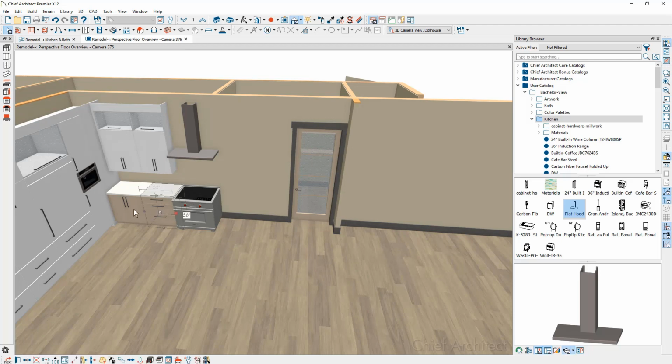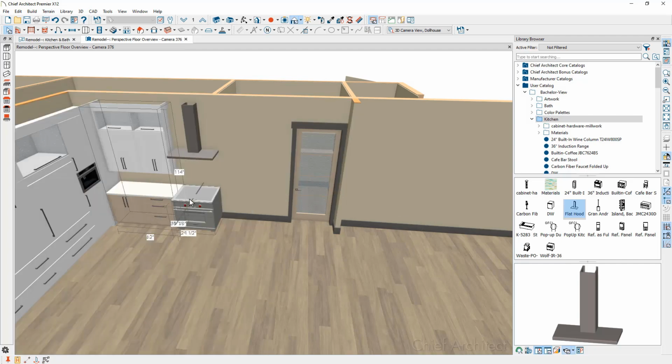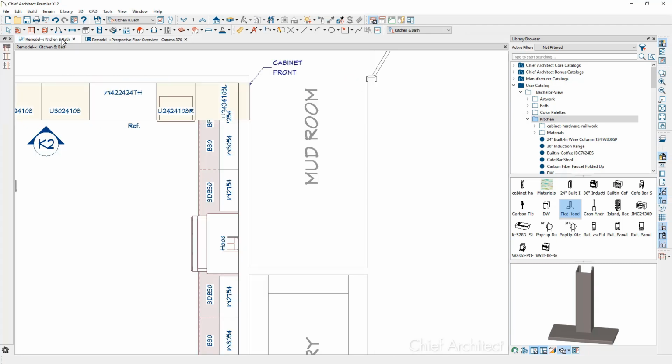Now I'm going to go ahead and select the base cabinet, hold my shift key down, grab both of those and both of the upper wall cabinets. Use the copy tool in the lower edit menu, copy, and then reflect about. Come over, find that cook range, and copy those cabinets and flip them over symmetrically. I'm going to return back into the floor plan view, and to create a wall elevation I'm going to use the exact same tool we did on the other wall. I'm going to come down here, use the wall elevation, we'll point and click towards the wall.